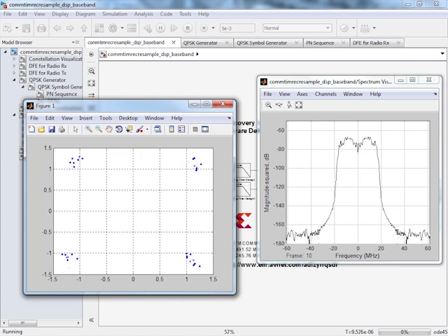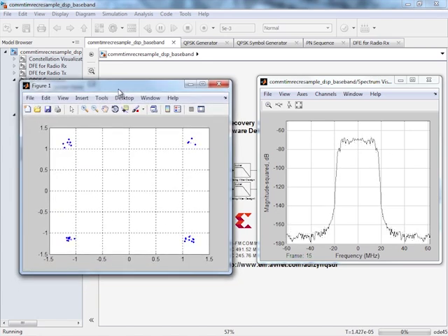And we're going to take a look at our system visualizations. Notice the sharp roll-offs of the frequency spectrum, which would allow subsequent decimation stages typically found in a digital down converter after the matched filter, although we haven't included any further decimation in this model. Also notice how the QPSK symbols are well separated on the scatter plot, which would ease the subsequent demapping of the symbols back into the data bits of the payload. So we've now confirmed that our symbol timing recovery algorithm is functionally correct.